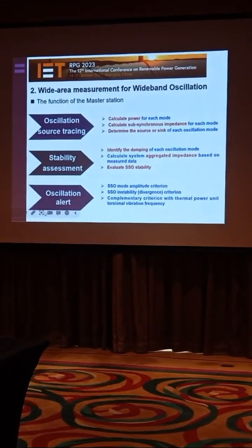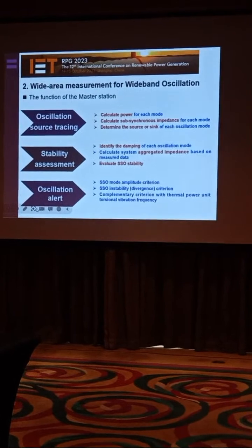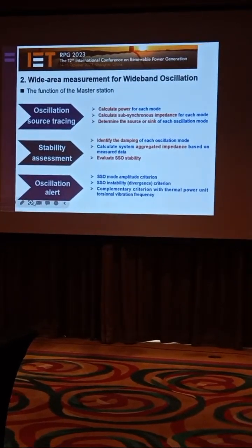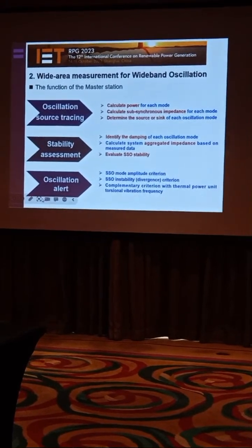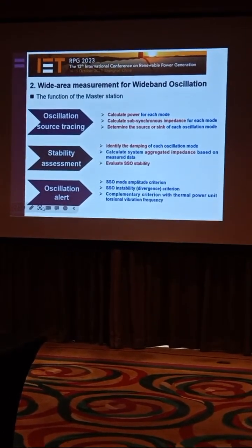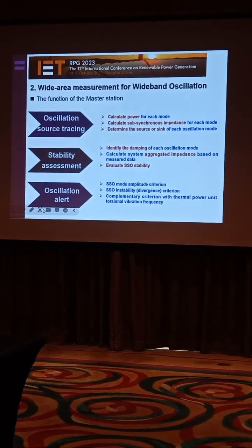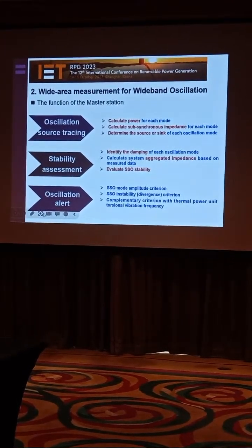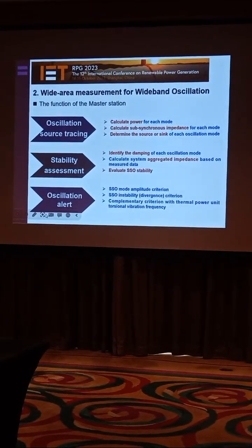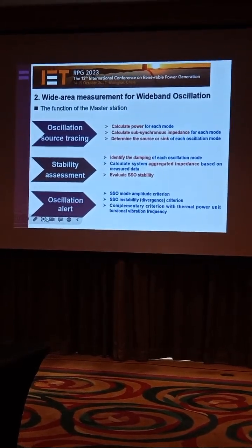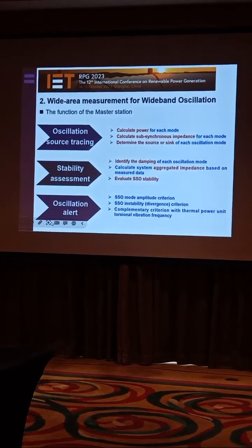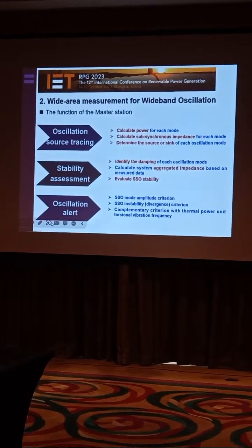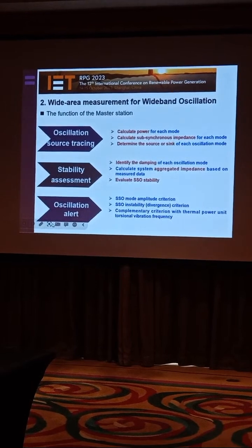The master station is responsible for calculating, organizing and analyzing data from the substations. Its functions include oscillation source tracing, determining the source and sink of each mode by calculating the power and sub or super synchronous impedance for each mode.